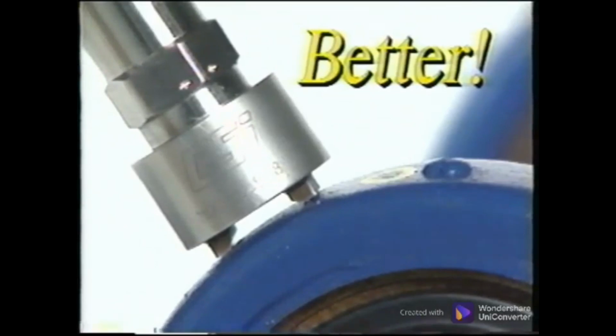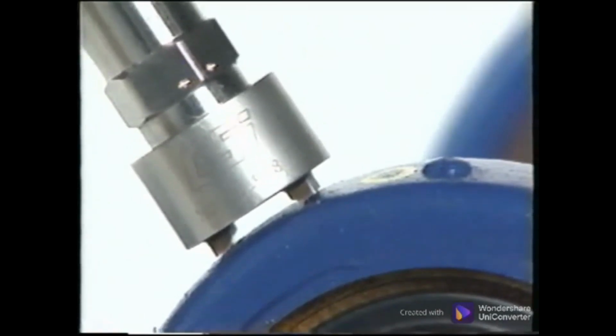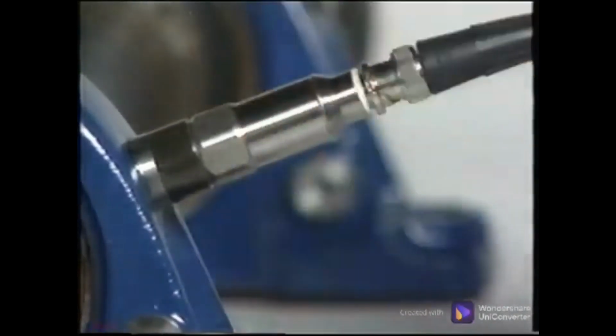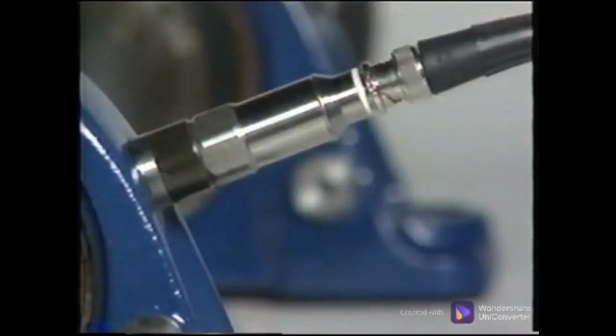The linear frequency range will be increased substantially to be sure to catch bearing degradation. Oftentimes, the pillow block bearing has rounded surfaces that cause the magnet-mounted sensors to rock. In cases like this, it is better to install a mounting pad for the sensor.